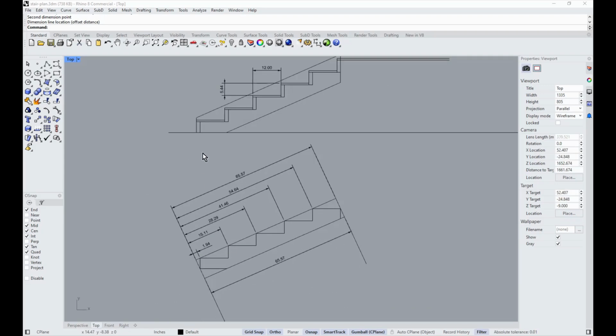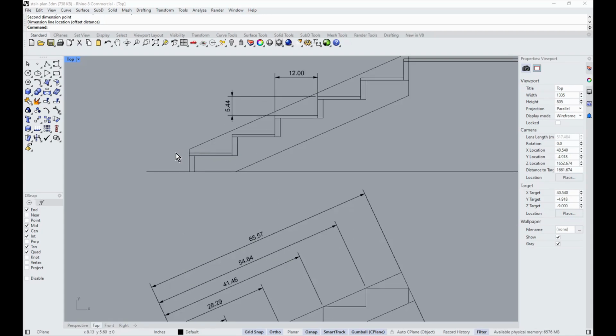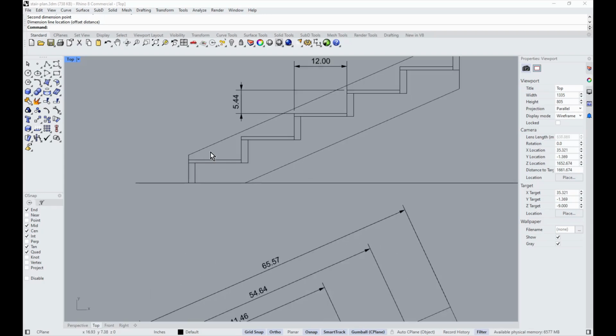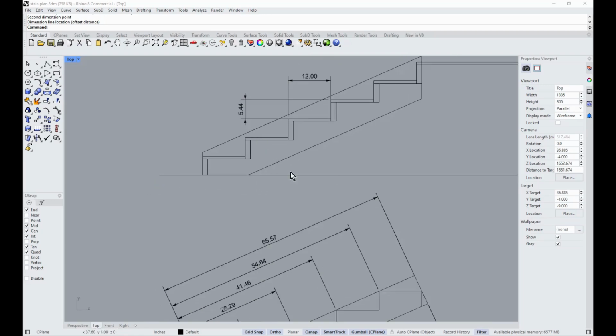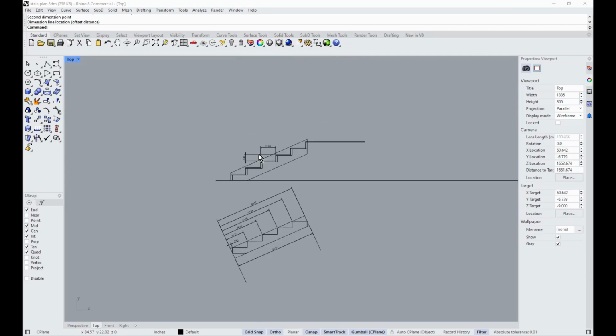Let's see here. So other things to note, my stringers, especially the ones on the bottom that touch concrete, were pressure treated, so we didn't have to worry about that. Don't ever use just white wood, aspen, Doug fir, Hem-Fir, whatever, and have it touch concrete. You've got to make sure you have something that's pressure treated, either green or gold pressure treating, like yellow lumber, or the green stuff works too when you make contact with concrete. So that's showing you this whole tread setup.